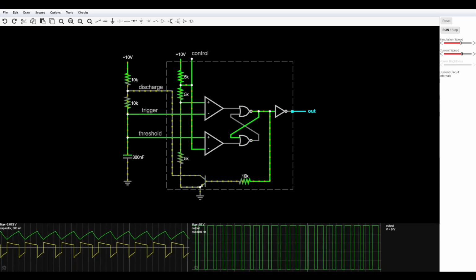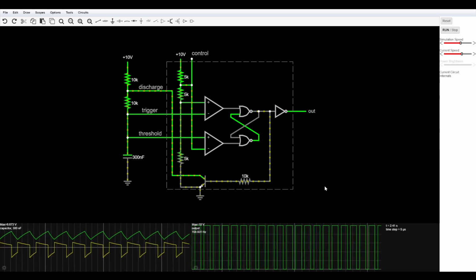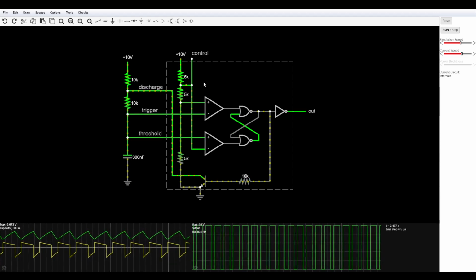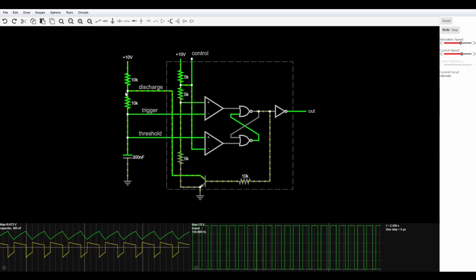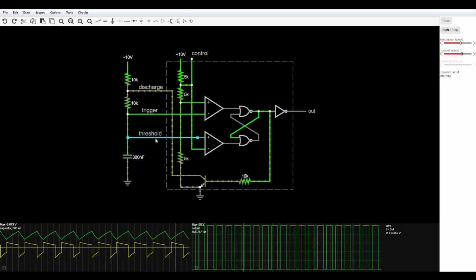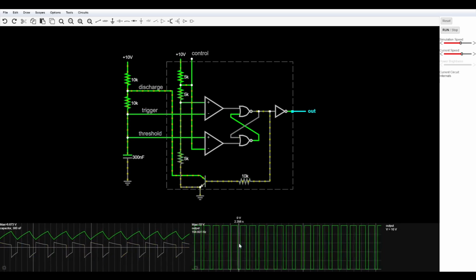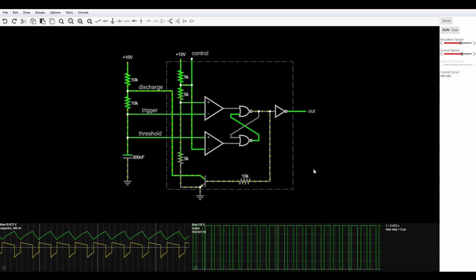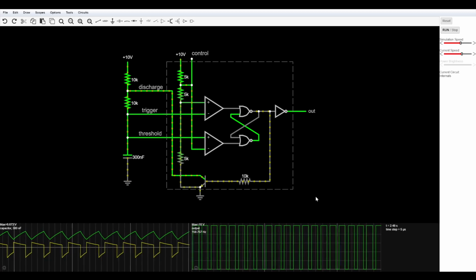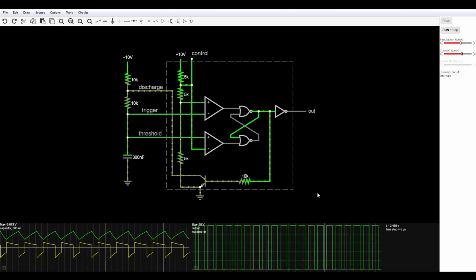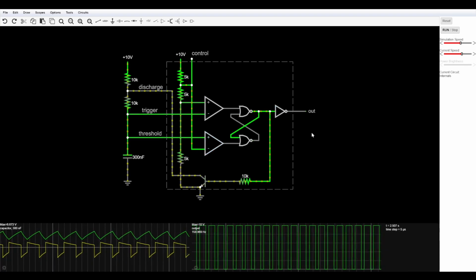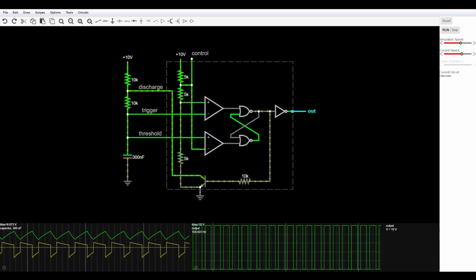All right, we're going to look at Falstad, and it's essentially doing what it did in every circuit, but you can actually see the internals of a 555: the discharge, trigger, threshold. It's not the exact same numbers, though, because I don't really want to mess with the internals, but this gives you an idea. In the actual chip, it's all transistors.